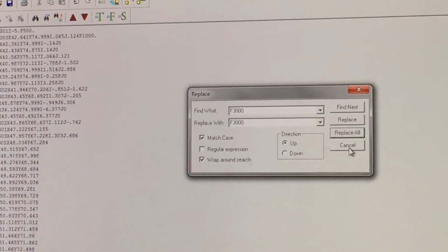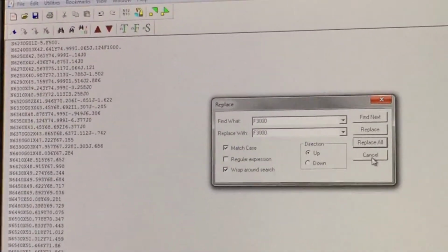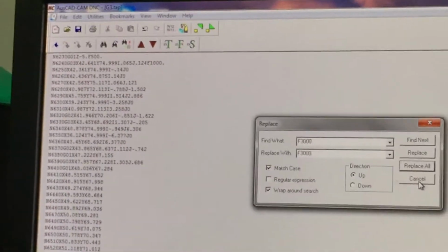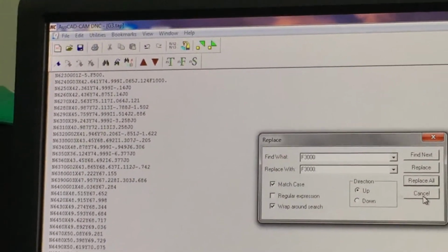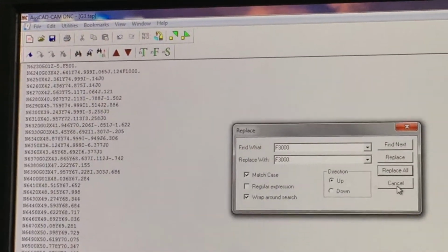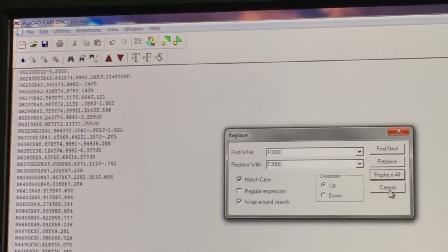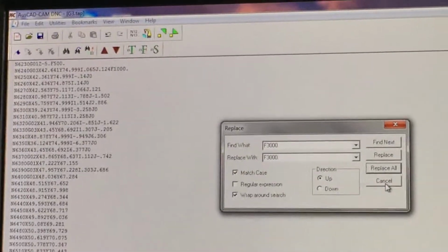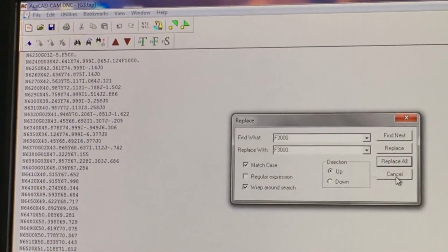This actually depends on your part design and the NC program. So every program, we need to change this. What is the feed rate? Feed rate is the speed of the axes moving, the XY that holds your sample. Remember in the class I said mm per minute.